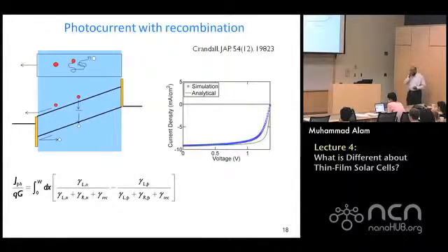Now, one thing I haven't been telling you so far is that this material is full of defects, right? Remember, low temperature deposition, all those grains crisscrossing, full of defects. Now, when you have things full of defects, then life is a little bit more complicated, because even in that case, I want to show that even if you put a blocking layer, it is not going to help you in making the current voltage independent. I'm trying very hard to make it voltage independent. It doesn't want to stay that way. Why not? What happens in this case? Why can I not make it happen?